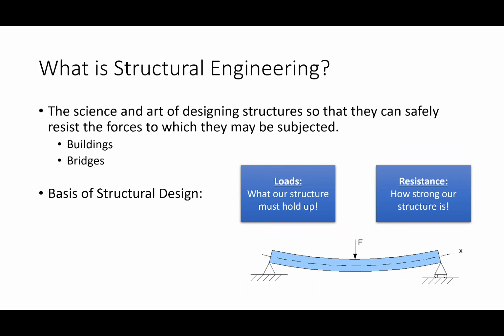So, for example, and I've used this example quite a bit in this room, we're in a classroom. If we look here in the roof, if we conceptualize what's going on above this drop ceiling, I can see a column right here, probably a similar column back here. So there's probably a beam stretching in this direction that's supporting the load of the floor above it. So what we would do in structural analysis is we would try and capture those loads. There's a number of ways we could do that. If it was a truss, we'd have method of joints, method of sections, shear diagrams, moment diagrams, all those nifty little tools we learned last semester.